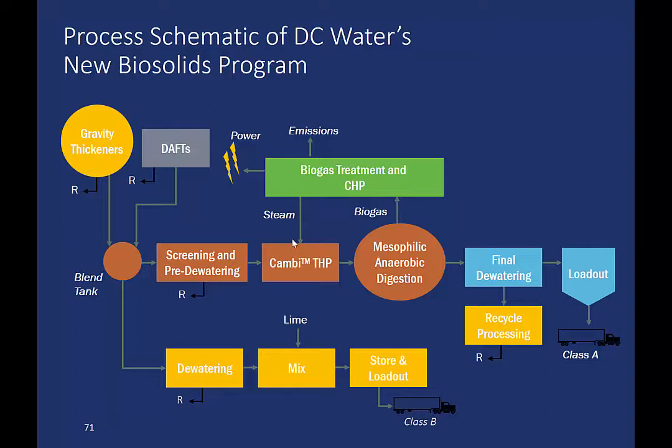If there are any solids that skip the digester, then you're basically going to have to buy lime, and you need to lime it all, because that's going to kill the pathogens. Without digestion, you don't have a pathogen kill step. And so what they do is they lime it, so the pH goes up to like pH 11 or 12, so then the microbes can't live, and then you apply it to the field.